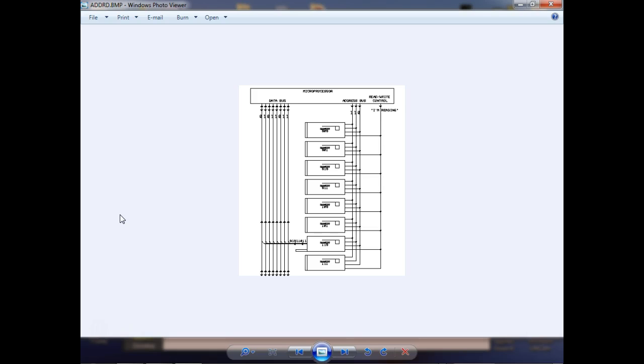Right now, data bus sizes are 128 wires, but basically we're only dealing with 64 at a time. That's a pretty good deal of information. Then we have what we call an address bus. The address bus is just a group of wires, and notice it's called a bus because we run the wire, or the conductor, out through the system, and then everything just does what? Just taps on it. We call these buses. So you have a power bus, you hear all these different names. So this is called a data bus. These are just a group of electrical conductors that run out all through the system, and then everything just does what? Just taps.